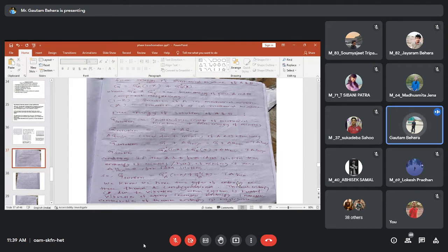You do not have any pure component. Because of addition of more components, more entropy will come into picture. That is called configurational entropy. Because more components means more number of arrangements can be possible. The more the arrangements possible, the more the configurational entropy, right? So we can have two types of entropy, vibrational and configurational, right? So basically, when we are talking about solutions, solid solutions or liquid solutions, in that condition we take the vibrational entropy as negligible. We don't consider vibrational entropy. We basically consider configurational entropy in that condition, right?